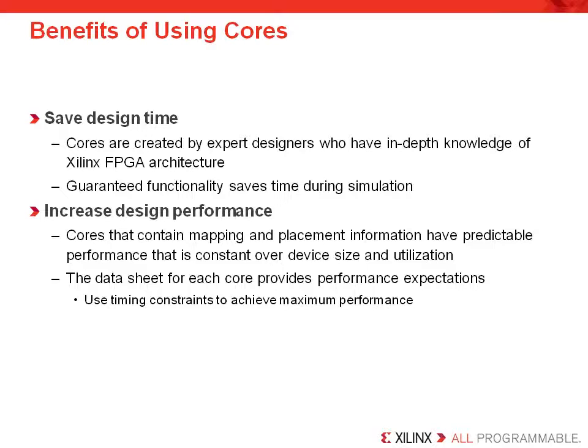Using cores saves a lot of design time, whether that time would be spent writing HDL to serve the same purpose, or completing simulation, or even debugging. Using Xilinx cores assures that you get a pre-optimized component that uses the best device resources to assure the best performance and minimum device utilization. Cores have been built, tested, and simulated. Their guaranteed functionality helps assure optimum system performance, but this will depend on your design and whether the core would be part of a timing critical path.